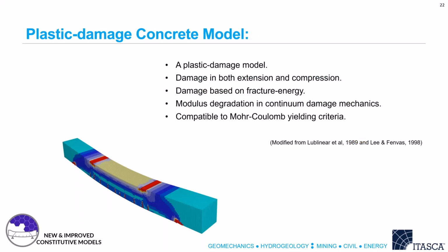Okay. The next new constitutive model in FLAC3D version 9 is a plastic damage concrete model. This model can have damage development in both extension and compression directions. The damage is based on fracture energy and the modulus degradation in continuum damage mechanics. This model has a yield surface compatible with our classical Mohr-Coulomb yield surface criteria.